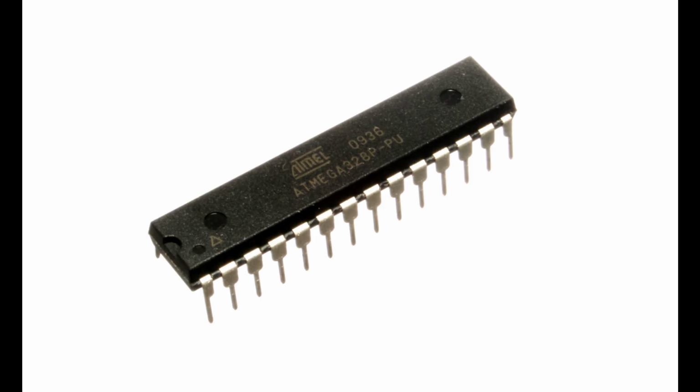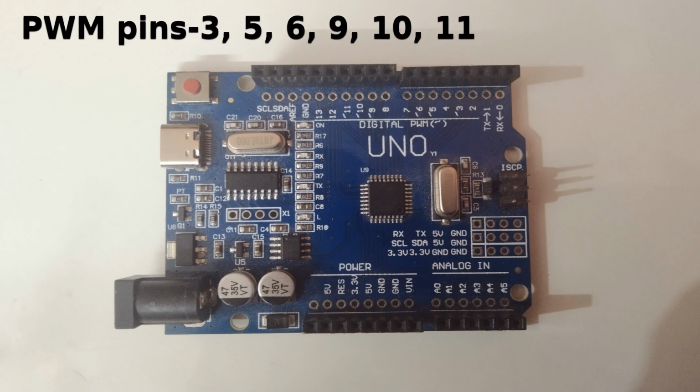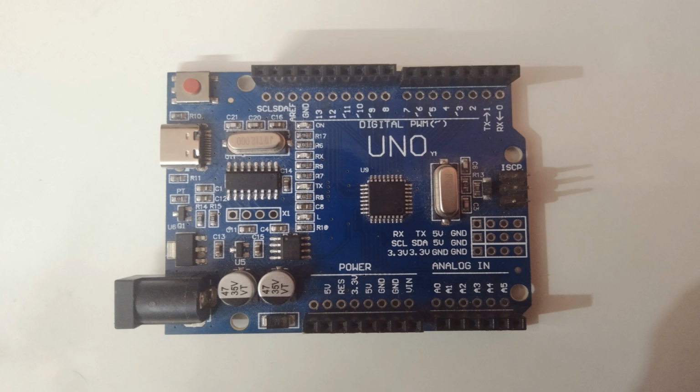Let's talk about the specifications and details of the microcontroller. Here the microcontroller being used is the ATmega328P, and the operating voltage is 5 volts, so it runs on 5 volts. The digital pins are 14 pins, of which 6 provide a PWM output, which is the pulse width modulated output. The PWM digital pins are pin numbers 3, 5, 6, 9, 10, 11, which can be used to control the motors, etc.